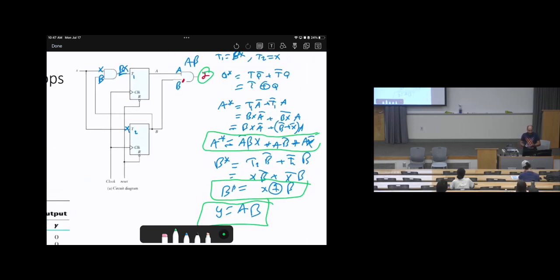The states are A and B, while the input is X. Is Y function of X? No. Therefore, Y, or the output, is not function of inputs. Therefore, in this example, we can apply Moore model if it is required. Why? Because the output is only function of states, not function of inputs. But you have the choice, or actually it depends on the question. If it says use Moore model or use Mealy model, or sometimes if there is no information, then just use Mealy model. Let's make it our default.